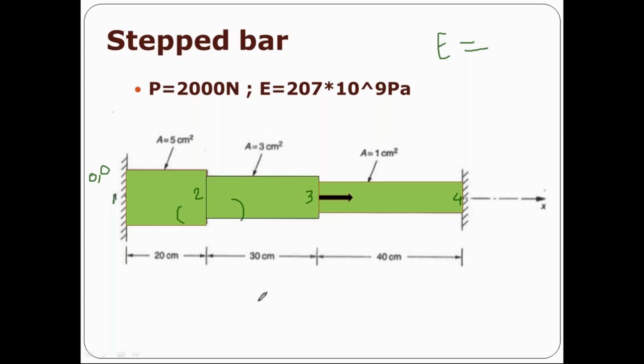Listen, when you are solving the numerical, you have to keep in mind one thing. All things should be in the same unit. When you are solving any question on ANSYS, ANSYS is not asking you which units you are using. You cannot set the units in ANSYS APDL. It depends on you, whatever numbers you enter. ANSYS assumes that you are entering all the dimensions in the same units.